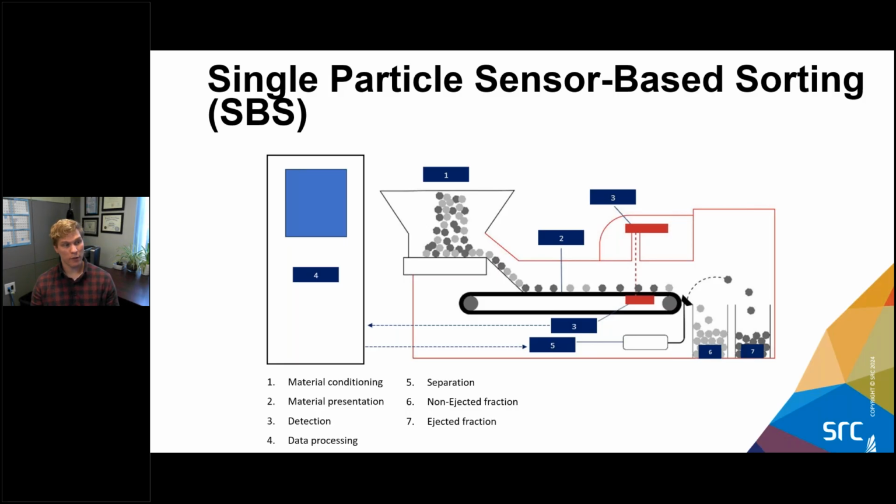But if for some reason you don't have a proper calibration, or there's some kind of not properly sized material, let's say, introduced to the system, you could misidentify a valuable particle as a non-valuable particle, in which case, let's say we're ejecting valuable particles, it wouldn't get ejected. And then you get the flip side too. If your definitions aren't good, you could identify waste as a valuable particle. And now you're just adding yield to your product stream, and you don't want to do that. But that doesn't happen too much if you set up the sensor properly. What's more of a concern are the mechanical inefficiencies.